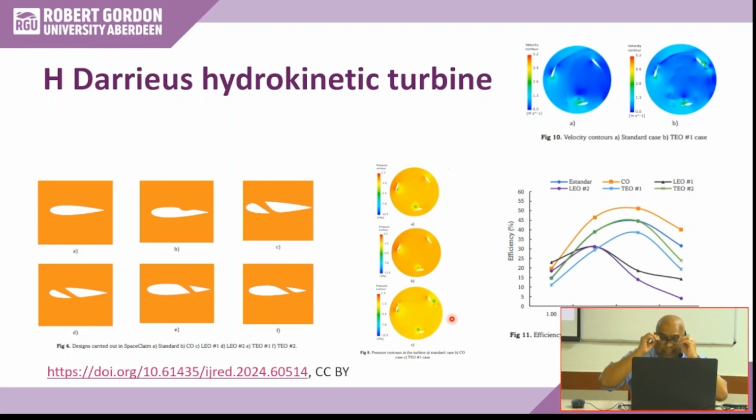And then you simulate in the computer, and then you see the pressure profile. Where is the pressure? You can look at the blade very carefully. This is a positive pressure here, negative pressure here, and this type of dimple and slot will create a different velocity profile and different pressure profile and try to manage the flow separation basically. And as a result, what do you have?